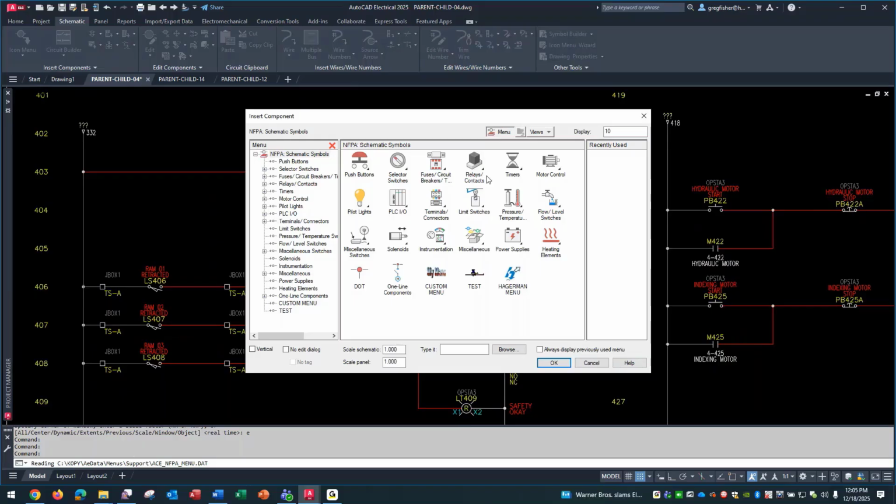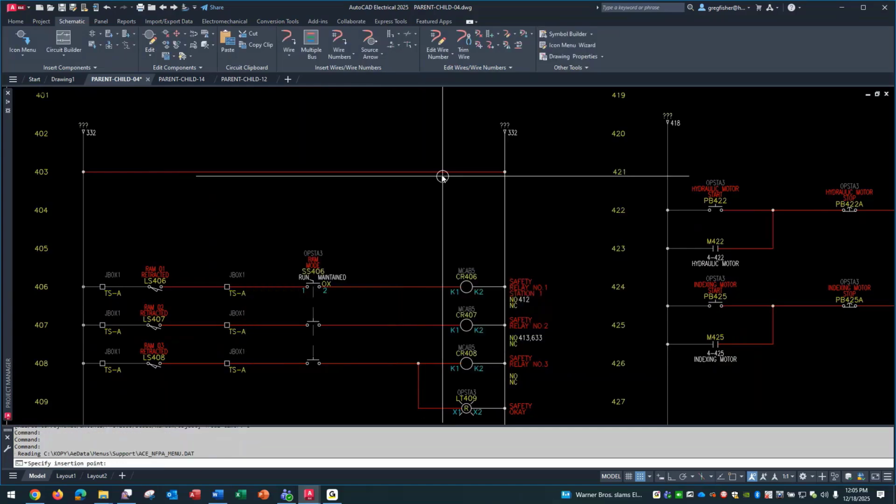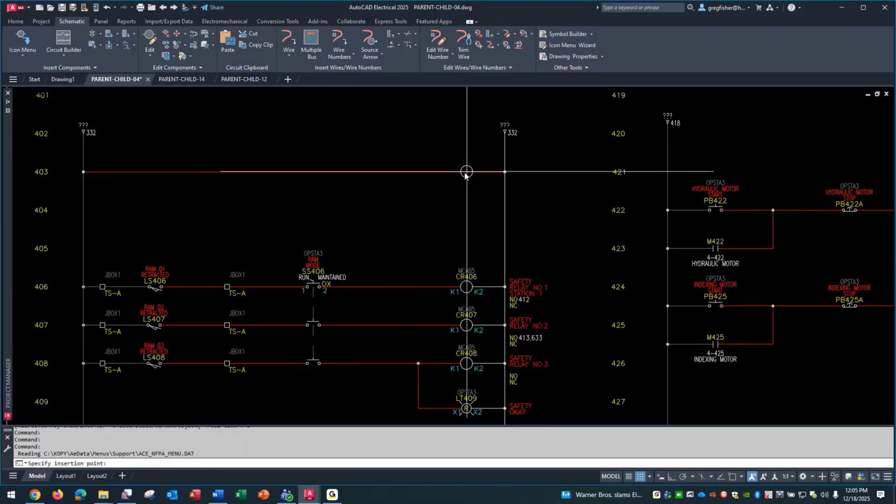So as a simple example, going back to the relay and its contacts, if I have a 2-contact relay that I've spec'd out as far as the catalog number is concerned and what I want to use to display that inside of a schematic drawing, I don't care what software you're in, we have to spread the symbols out. We got a coil, we got contacts, so it's not just one component anymore. So if I do insert a relay coil parent symbol, let's just call this a parent symbol.